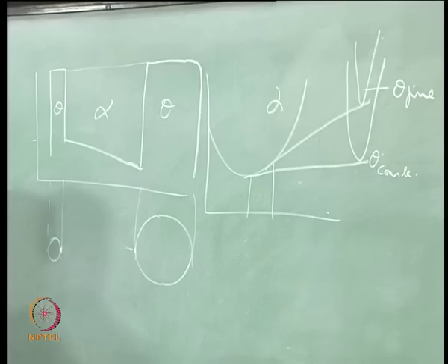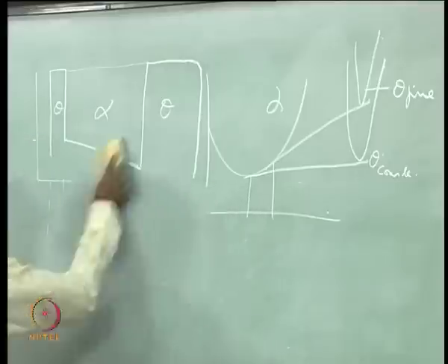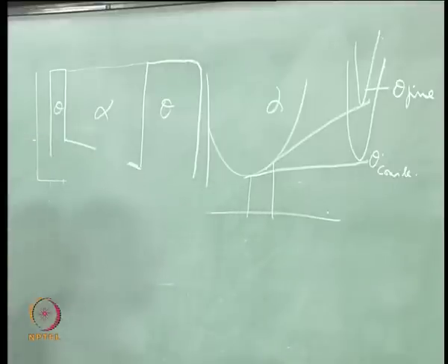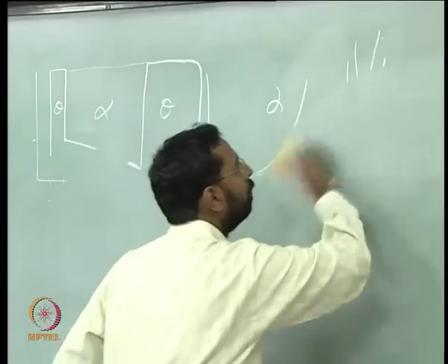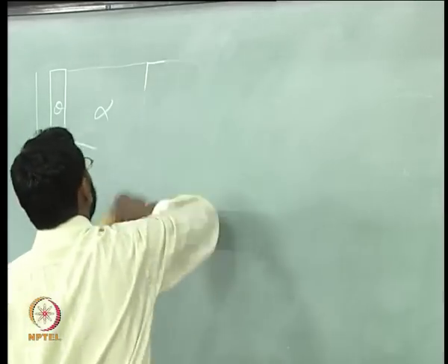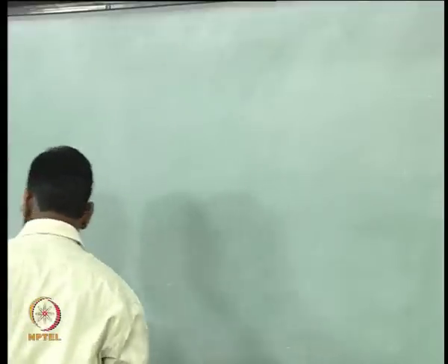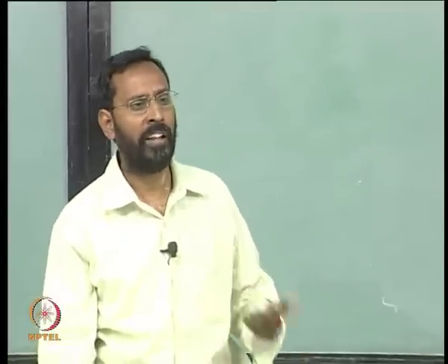Okay. In the precipitation of ferrite from austenite, higher undercooling creates Widmanstätten. Correct. Again, the same situation as what we see with coherent precipitates. Widmanstätten precipitates are all either coherent or semi-coherent. Yeah, but they still precipitate at the grain boundary.